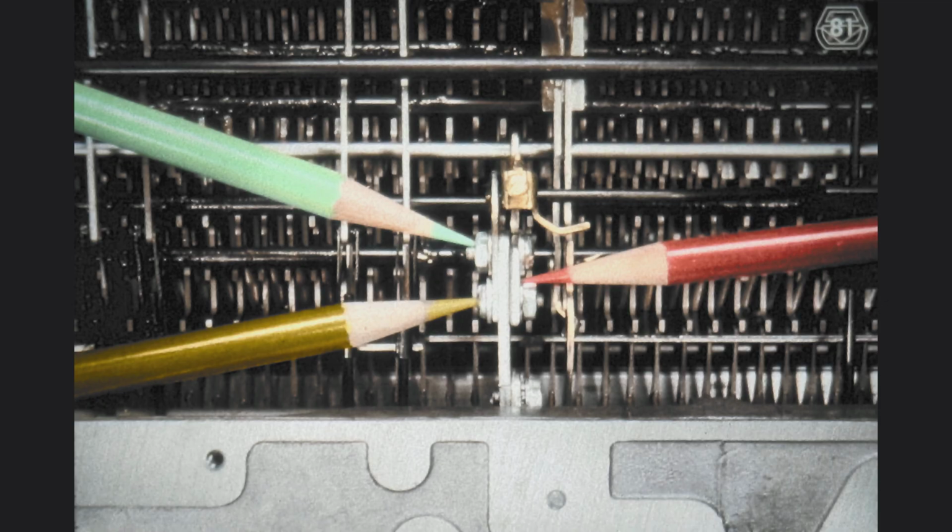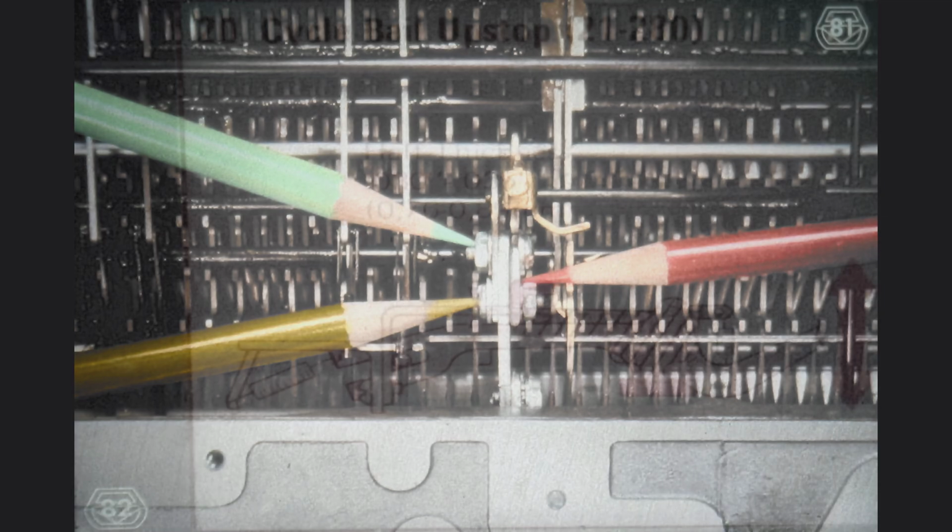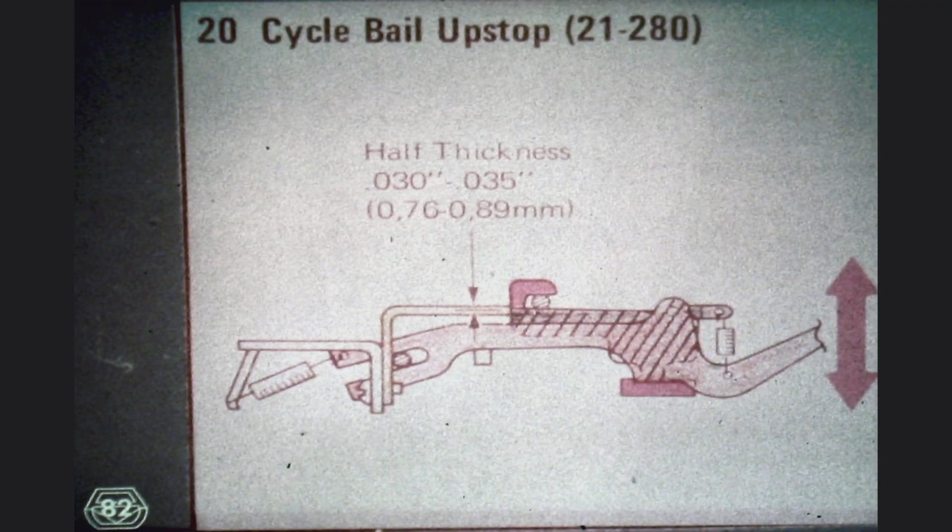You may find it worthwhile to review this sequence again. It contains the steps we must follow for the cycle clutch latch pawl bite adjustment. Remember that the condition of this bite may be one of the causes of flicking. Now make sure that your machine meets the specifications shown in this adjustment frame before continuing.